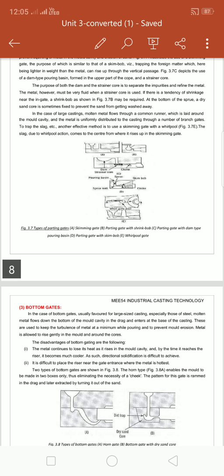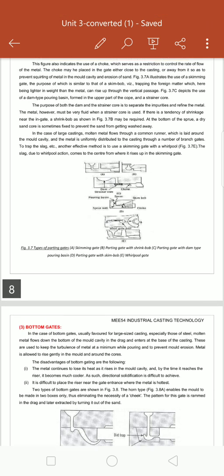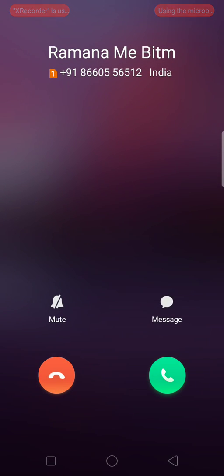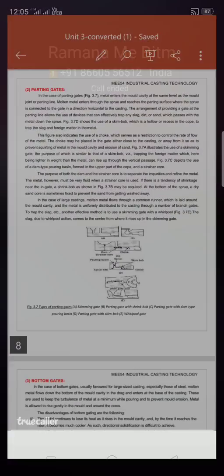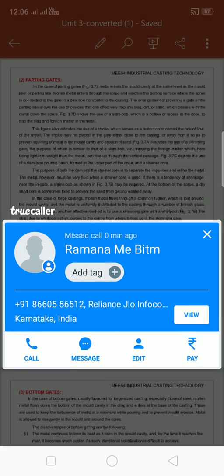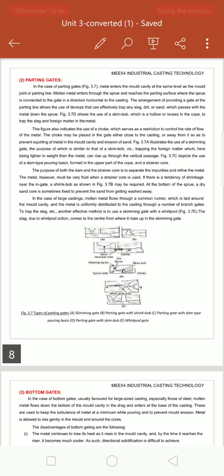Clay refers to particles whose size is less than 20 microns. It has a very large surface area and a very high affinity to absorb a large amount of water. When clay comes in contact with water, it becomes cohesive and plastic. Clay mainly consists of silicates of alumina. Clays are classified as montmorillonite, bentonite, kaolinite, illite, and fire clay. Binders are the materials added to base sand to give binding cohesion and strength to the sand mix after ramming them.